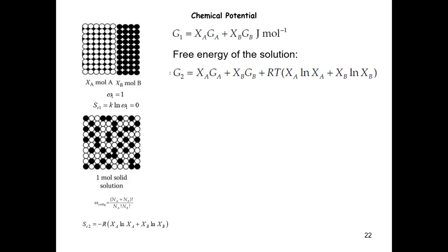It doesn't matter whether the bonding neighbors are A or B type, they have the same contribution of the interaction energy. So from the interaction energy point of view, the system does not distinguish different neighbors, and there will be no contribution from the enthalpy due to the mixing. The only contribution is this part, which we call the contribution from the entropy of mixing, and we derived all of this together.